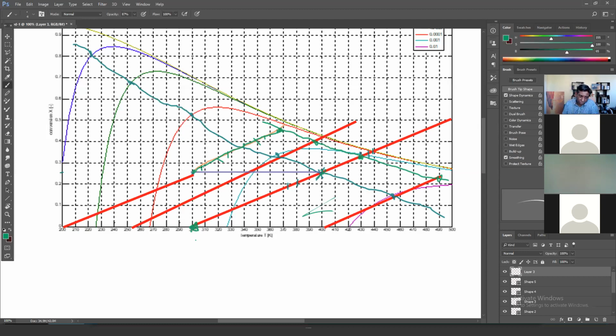With the PFR, if we chose to stop here, right? Remember, with the CSTR, we went and stopped on the maximum rate line. Let's just draw that again. So remember, this is our maximum rate line. With the CSTR, we knew the whole CSTR was sitting on that maximum point. With the PFR, however, if we choose to stop here, then that means only at the end point of that PFR.